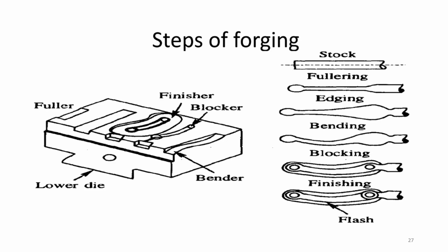The solid will be shrinking after solidification. So that part, when the liquid changes temperature, the liquid shrinkage will be dealt with by the riser. So extra material will keep on coming from the riser.